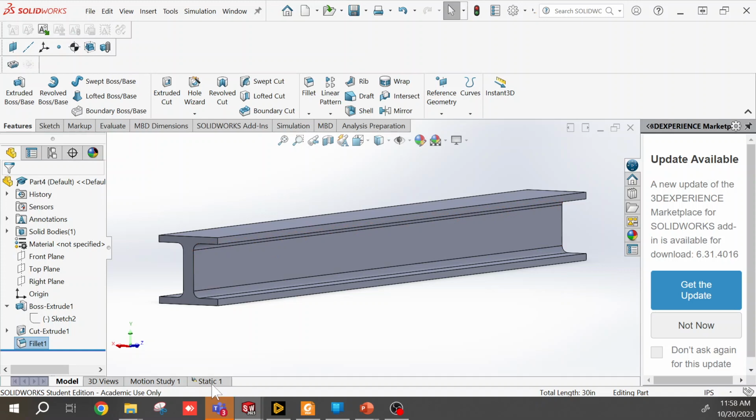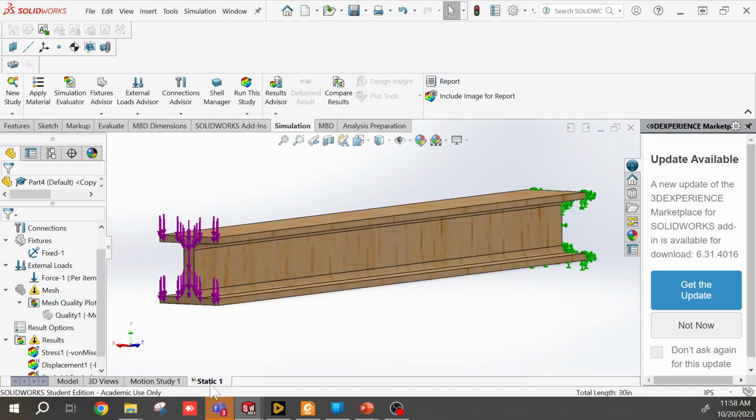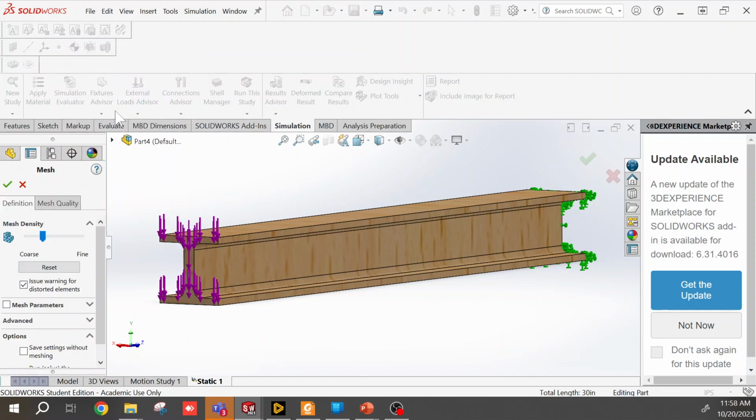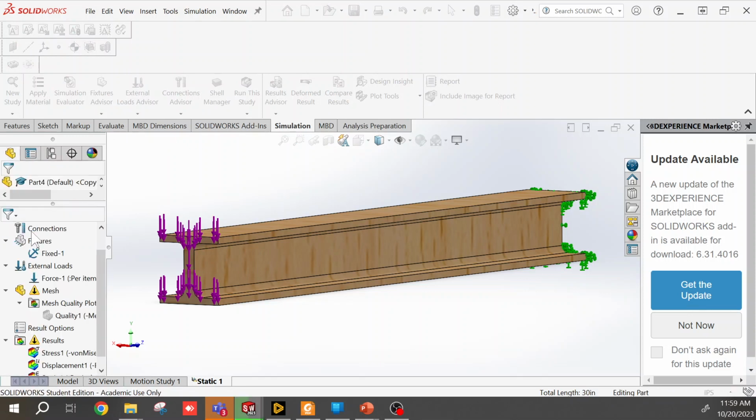I'm going to go back to the static simulation, and you're going to see that our mesh here and our results have kind of this yellow caution mark on them. The faces that we've assigned for the strength and load haven't changed, but our mesh should change now because we've changed our geometry, and the results clearly are out of date because now we have an I-beam profile. So for us to remesh this, it's as simple as right-clicking, create mesh, and let's make it slightly coarse so it runs quickly.